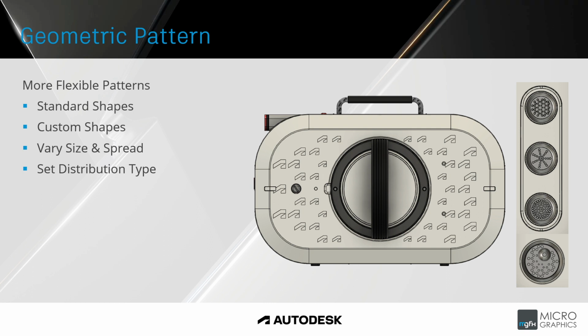Not only this, but you can also customize the shape as seen on the side of the camera in the main image. That's the Autodesk logo that was created as a solid body in the part, which is then used as the source and patterned using this tool. You can use standard or custom shapes, but with this tool, you can also change the size and spread of the shape across the selected surface. Lastly, there's the distribution type. Hexagonal at the top right-hand image there, radial in the center of the 3, and lastly we have circular distribution. So the 3 patterns on the right-hand side represent the 3 different patterns. Just to note, the 4th one at the bottom is a hexagonal distribution, same as the top one. We're just distributing a different shape on a different surface.